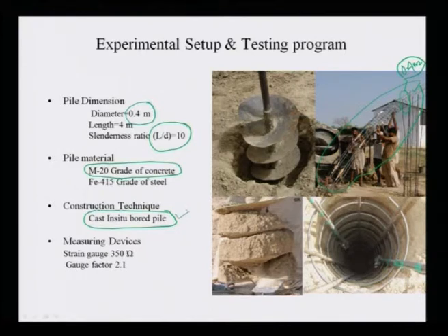There are different classifications of piles. If I make it into two parts, one is the cast in situ bored pile, the other is the driven pile. In the case of a cast in situ bored pile, cast in situ means the casting has been done itself in the field.